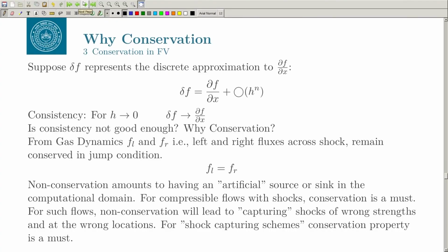Similarly, if you are using a boundary condition, let us say some kind of Dirichlet boundary condition, like the wall boundary conditions, on those boundaries you do not have this conservation being applied in the finite difference case. In the finite volume case we apply it even on the boundaries. So, the conservation is guaranteed in the finite volume, both the local conservation as well as the global conservation.